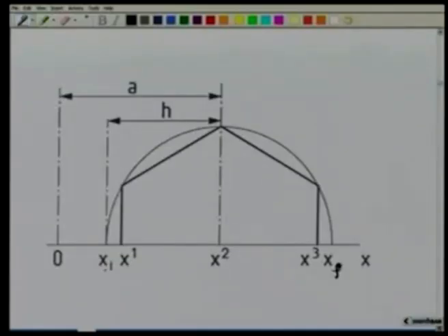Before I explain the different types of problems with reference to a 4R linkage, let me continue our discussion a little bit with the Chebyshev spacing of precision points. As I said, suppose we have to satisfy the requirement in a range of variables starting from xi, that is x initial, to xf. We have already seen how to choose the various precision points xj.